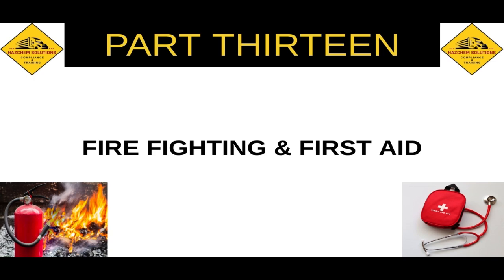Remember to go over all the prescribed signage that is relevant for the vehicle. I'm just going to give you the basics. You must have 3 placards on each side that is relevant to the dangerous goods being transported. You must have 3 stickers on each side. Remember, it's the no smoking sign, the no flame sign, and the no cell phone sign. There must be a dangerous goods hazard warning in the front. That is the orange diamond in the front of it. You must have the basics of 2 fire extinguishers with quick release brackets. You must have an operator card that is registered for category D. Those are your basic vehicle requirements.